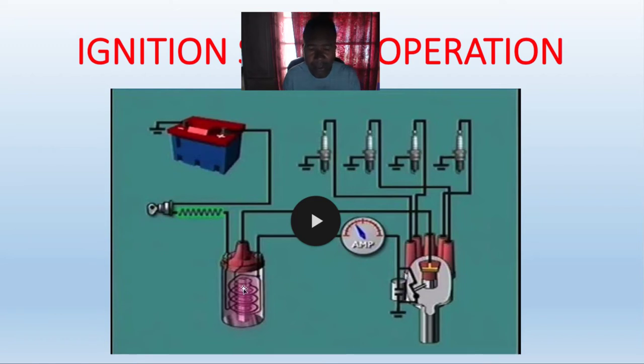Now think about this. We've got positive here, negative here. That means we have power, a load, so this side has to be the ground. What grounds it out is the points, old school for right now, something called a set of points. When the points are closed, the coil is being saturated or charged up, filled up. A magnetic field is being built. When the points open up, it collapses and you get a spark out the center tower from the secondary ignition.